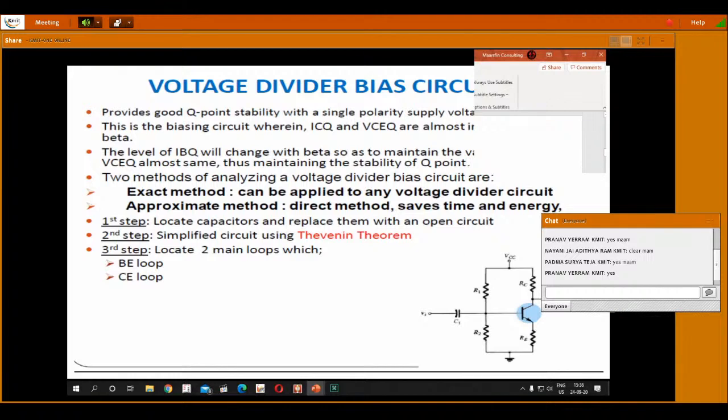In order to nullify the additional DC signal at the output of the amplifier stage, which can disturb the quiescent values of the second stage, we also provided C2. So to analyze this circuit, we just open circuit it, because for DC signals it simply acts like an open circuit with infinite resistance.